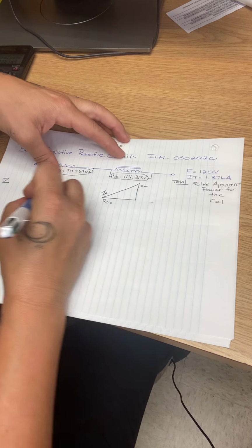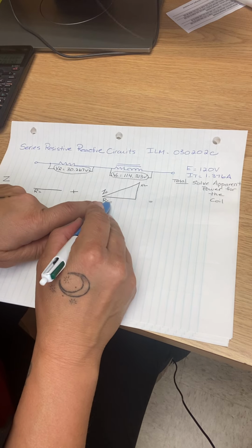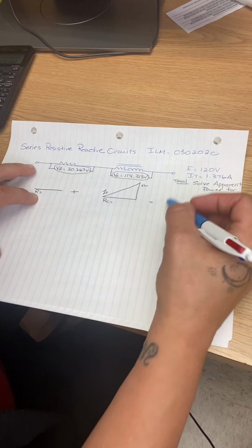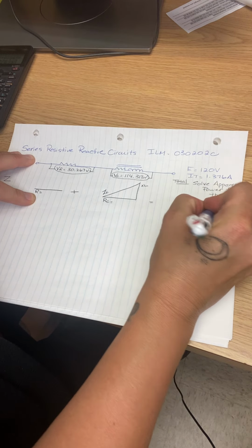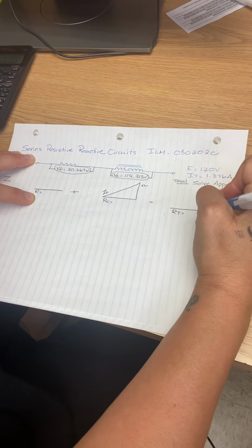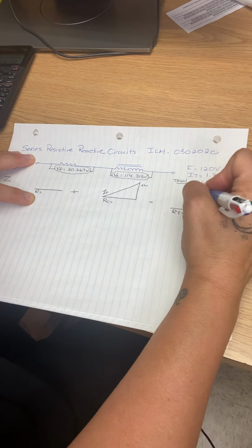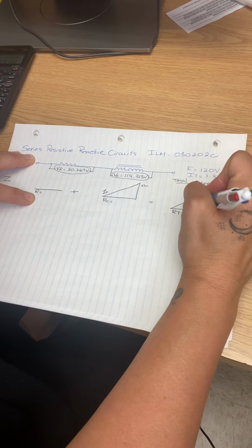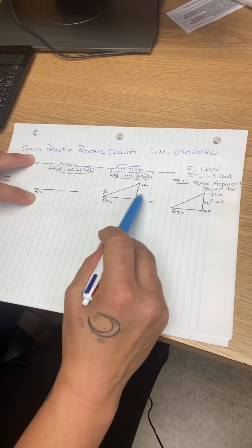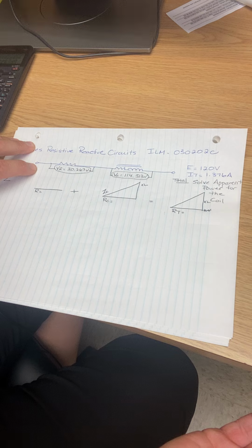So the resistive portion of my lamp is in phase with the resistive portion of my coil at 0 degrees. So these two values are additive. That would give me an in-phase component of a resistance total because they're in phase with each other. And then my vertical would be my XL. So whatever value of XL is here would be brought over to my circuit total because there is no component of inductive reactance or capacitive reactance found in the circuit.